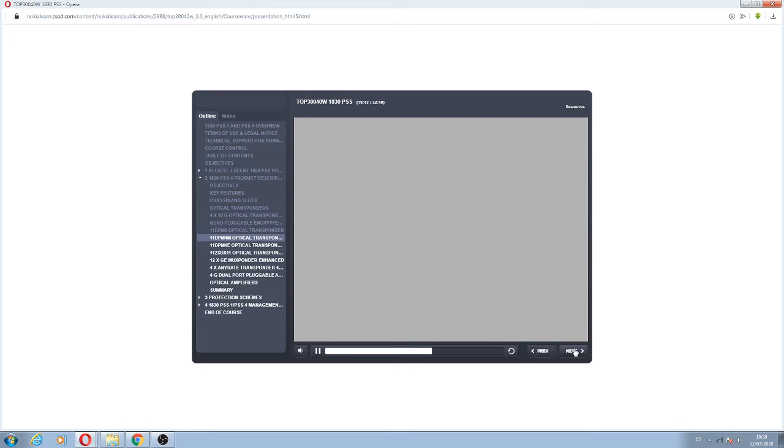The pack supports ODU0 and ODU1 level ESNCP. The pack supports standard GCC0, GCC1, and GCC2 functionality at line side. Terminal loopback and facility loopback are supported independently for both line side and client side of each port.